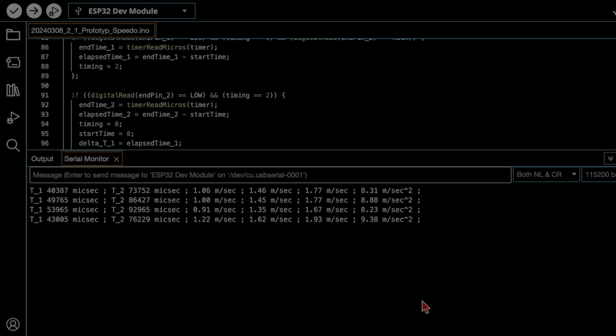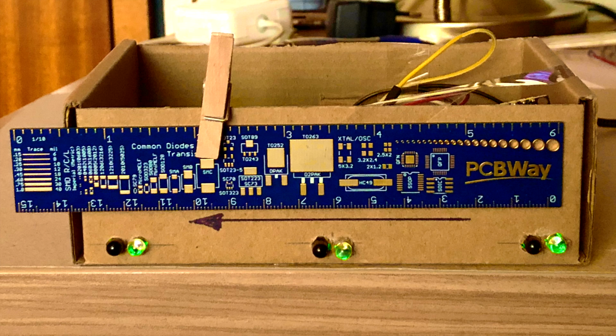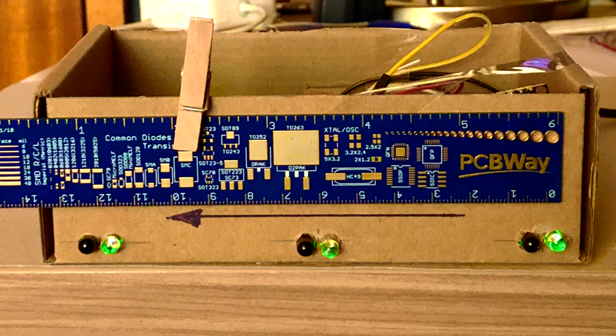But okay, so far my test setup is a bit inaccurate and shaky. First, the sensor's measuring cone is getting wider depending on the distance to the sensors. As an effect of this, the trigger point depends a bit on the distance to the sensor. In my first experiments, this might have caused an error of 5 to 10%.